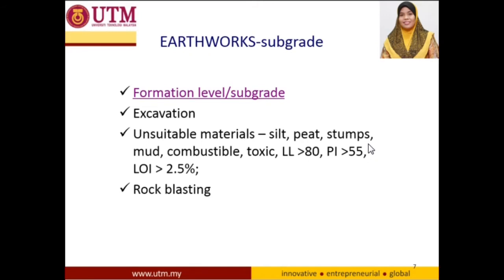The specification of unsuitable material can be referred to as a liquid limit of more than 80% and a plasticity index of more than 55%, and also susceptible to spontaneous combustion, where LOI or loss on ignition is specified as more than 2.5%, according to the Public Works Department specification or JKR specification. And then any hard material such as rock needs to be blasted.